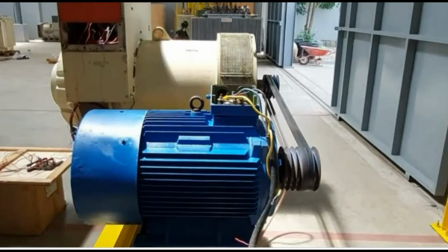Look at the transformer the community uses and ask what the capacity of the transformer is. The transformer capacity will tell you the community's consumption ratio, the capacity they can consume. This one is 500, which means it can take the whole community and still have a reserve. If my community has 300 kilowatts consumption and I have 500, I already have 200 in reserve. So let's continue.